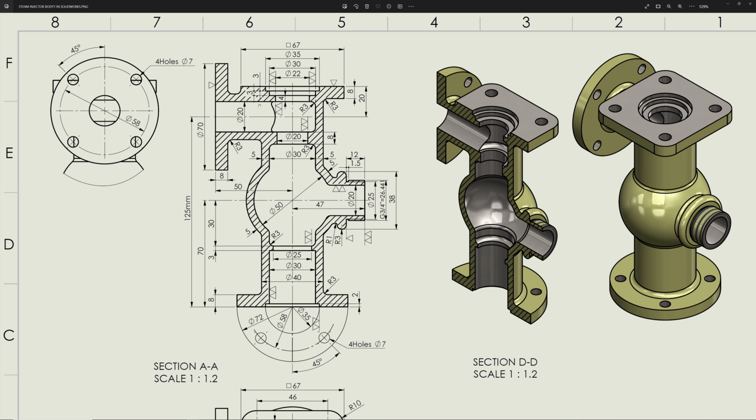Then let's go straight. Then there is one flange 8 millimeter. So we will reduce this 8 millimeter up to this center line 125, then this 120. So 145 minus 8, 137 is going to be, and this width also 40.